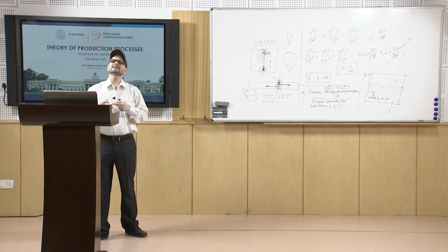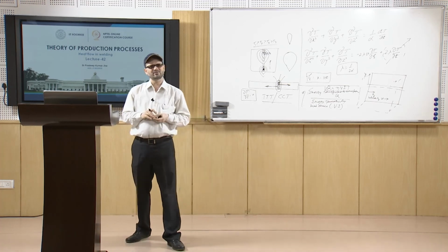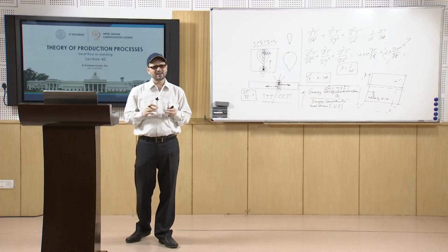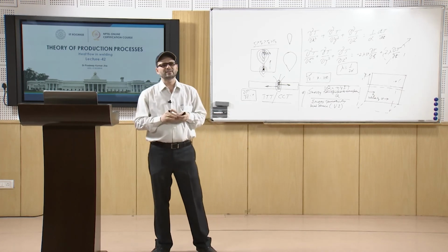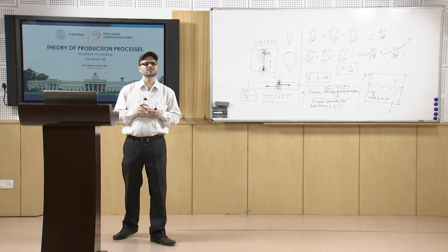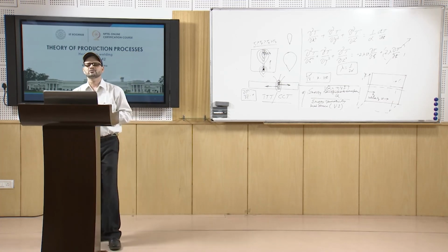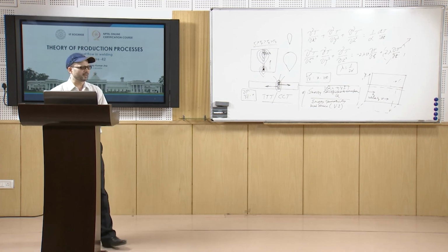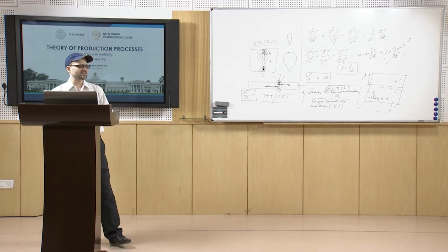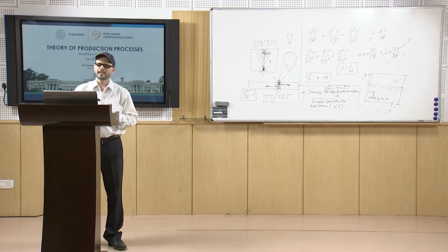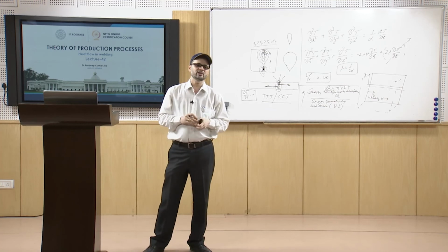Now, if you take the example of laser welding, here the efficiency will depend on the wavelength and energy density of the laser beam, the workpiece material, surface condition and joint design. Many times, if you take very polished surfaces like aluminum or copper, the reflectivity is quite high and then you have very low efficiency.